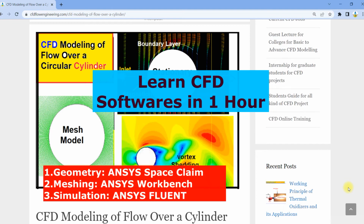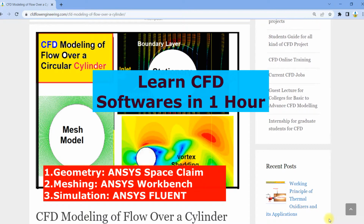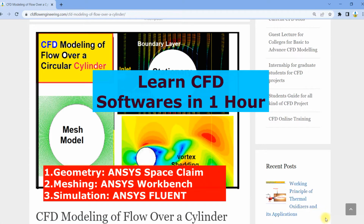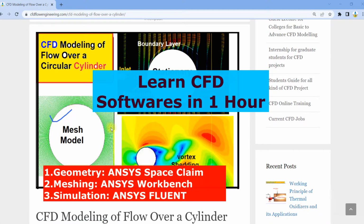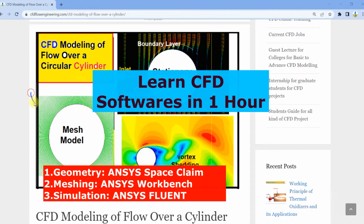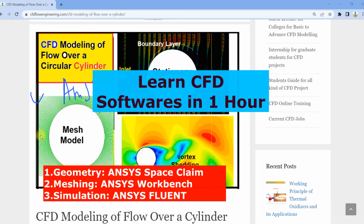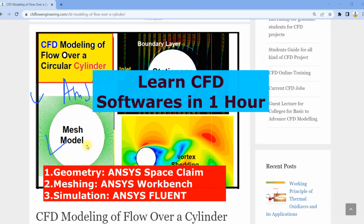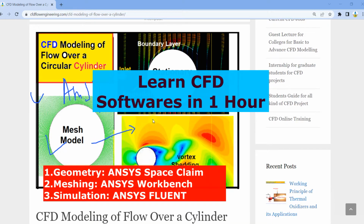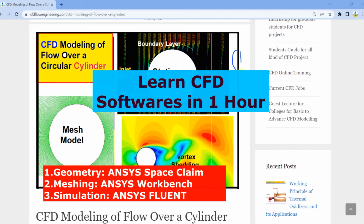In this tutorial we learn how to use ANSYS CFD software in order to model flow over a circular cylinder. First, we have to create the geometry in ANSYS SpaceClaim. Then you have to create the mesh model in Workbench, followed by simulation in ANSYS Fluent. Please note that three software packages are required.